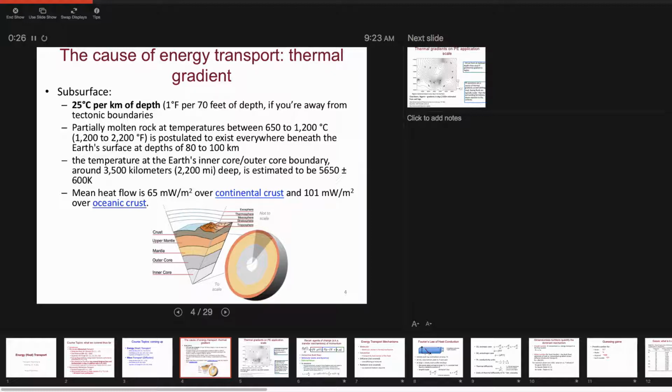So just like we had in any type of transport, for transport to happen, we have to have a gradient. Now, in momentum transport, our potential was the difference in pressure, or gradient in pressure. And also what caused our friction along the way is differences in velocities. Inside of the fluid, these different velocities and local changes in velocities cause internal shear stresses. Now, in energy transport, the essential difference that is getting evened out is that in temperature, or thermal gradient. Temperature field in itself is a scalar field, unlike velocity field. So the treatment of this is a little simpler mathematically than it is for momentum transport.